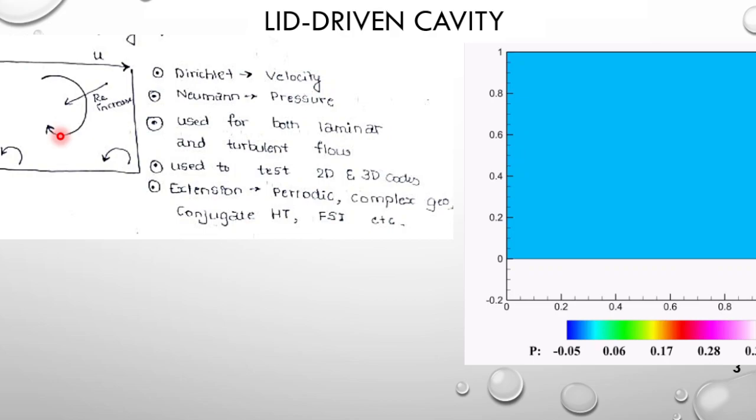Now the last case is fluid structure interaction, which I have worked with in my PhD thesis. So similar to what we do for the Navier-Stokes equation for fluid, we solve momentum equations in structural dynamics. We use some Kirchhoff stress strain transformations, like how you write sigma xx is equal to 2 mu into say dou u by dou x and all those things. So we have Kirchhoff stress strain transformations in our computational structural dynamics. The momentum equations almost remain the same. So we try to discretize that also, and then we couple it with the fluid.